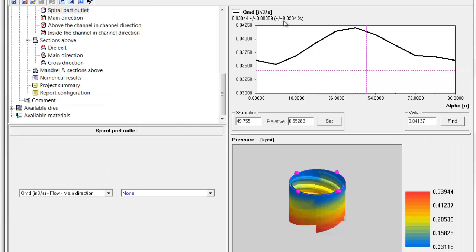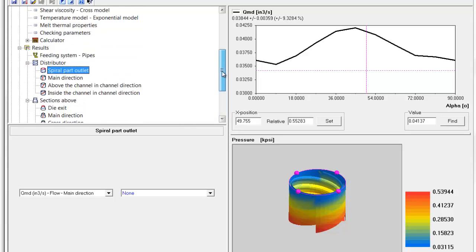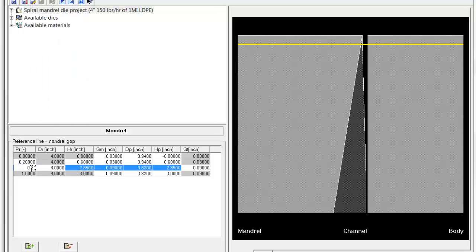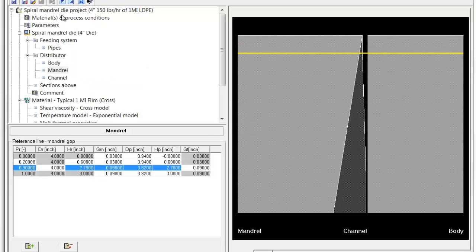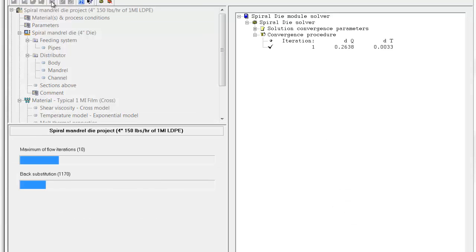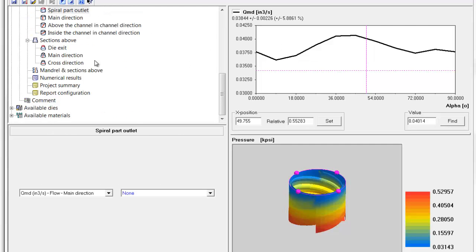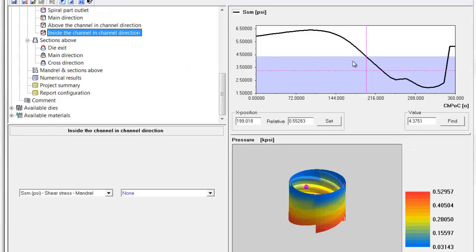And we see now that it got worse, so we're going to step back and go back to 0.90, and here we get an acceptable distribution, and we have our shear stress hitting our critical value above 55% of the channel, and our low values of about 2 psi near the very end.